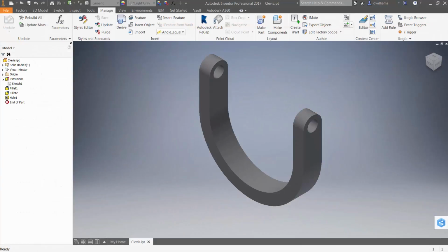The two distinct modeling techniques, often described as skeletal or table-driven, have as their basis the sharing of common parameters between multiple parts or assemblies. That way, if certain of these shared parameters change, all of the dependent parts and assemblies update to reflect those changes. Let's take a look at the parameters of this clevis part.